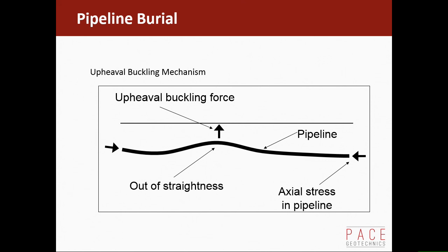And the upheaval buckling force, what you get is if you get a slight out of straightness, so the pipe profile may not be perfectly flat, that buckling force will concentrate there, just like a surface laid pipeline. If you've got that, it's effectively acting as a buckle, so it's feeding into that point. Same with a buried pipeline. And what we're relying on is this soil up here to try and hold the pipeline down.